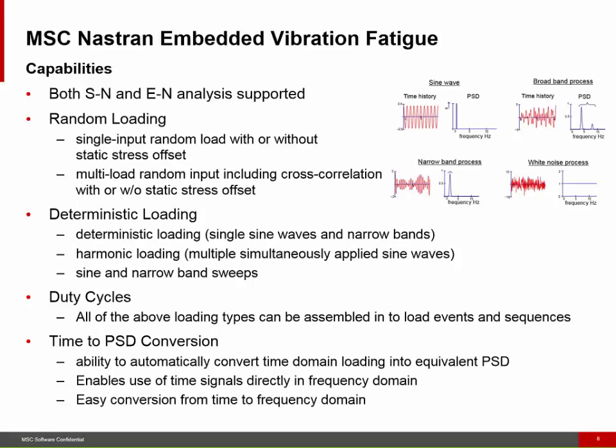And in addition to this, we have the capability to automatically convert time domain loading into equivalent PSDs, so going from time domain loading into frequency domain. That is done in the vibration fatigue using the FFT utility, which is provided within our capability.